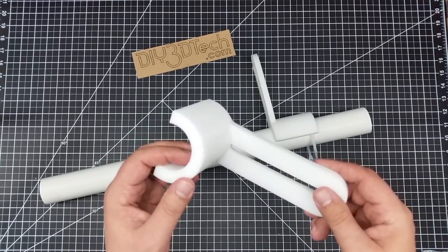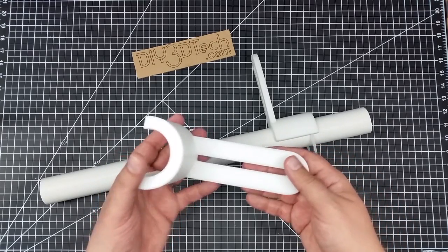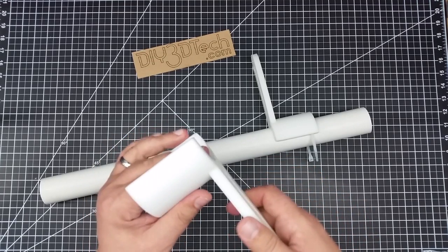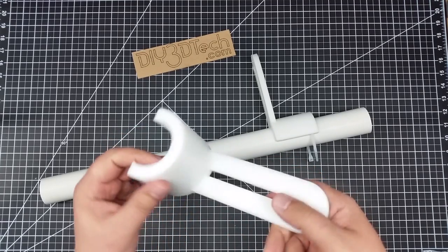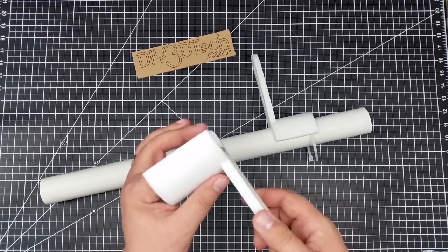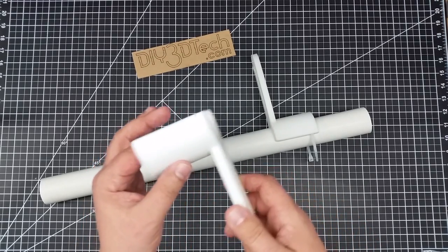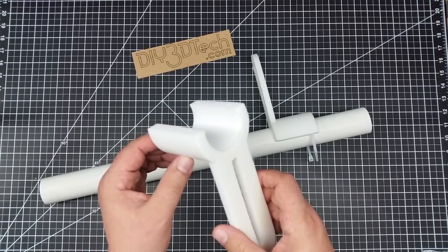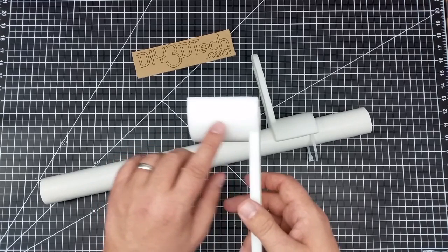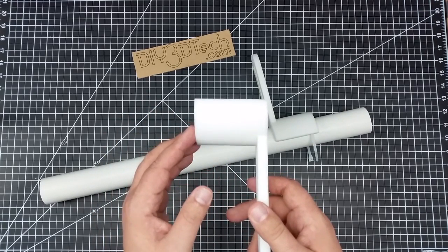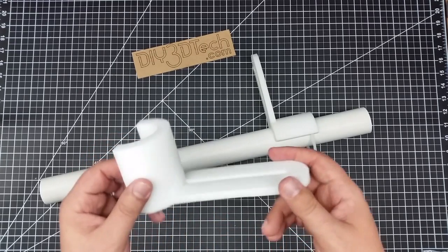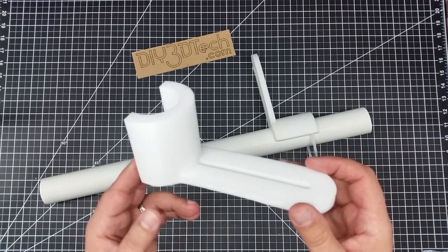So all in all, I'm very happy with this. Very lightweight too, seems to be very durable. I haven't done any really destructive testing, but it really seems very well put together, kind of printed a bit more like PETG or TPU than ABS or PLA. The layers are very fine. I printed this at a 0.3 layer height, I think with 25% infill, and very nice. So anyways, happy with the way it turned out.